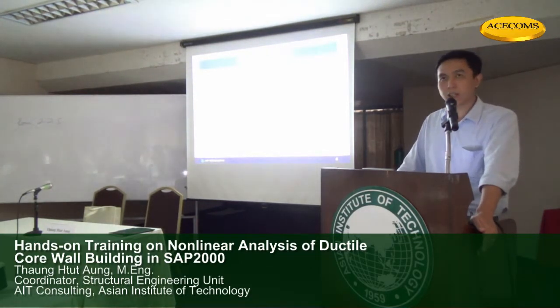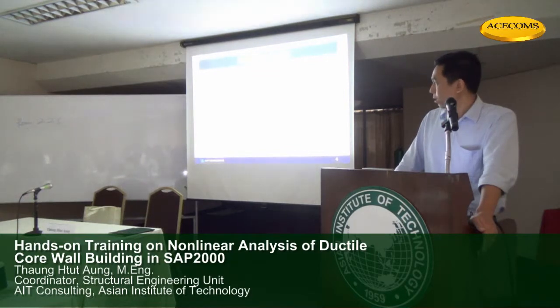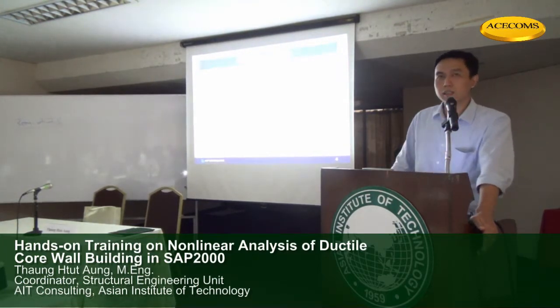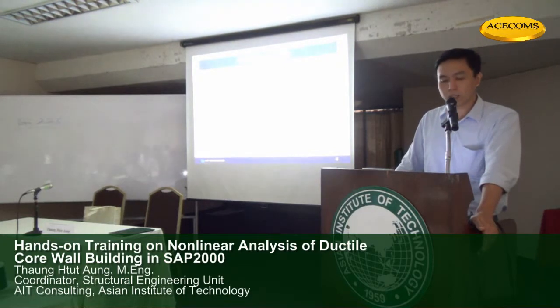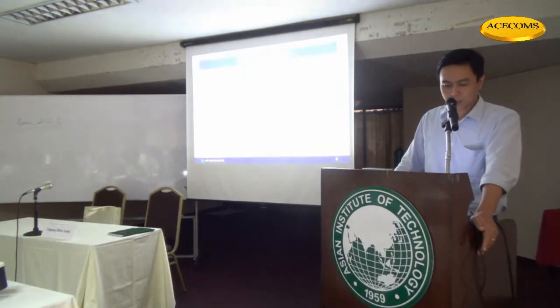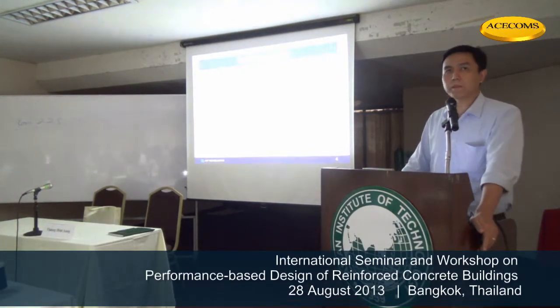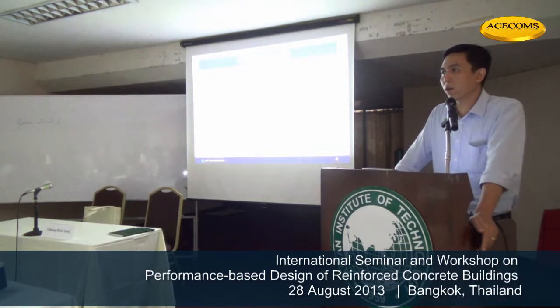And also check the natural periods. If the natural periods are very long, we have to stiffen the structure. And also modal participating mass ratio. From that information, we can determine whether the higher modes are dominant or not. Then we have to check the base shear. Base shear coming from the seismic loading as well as the wind loading.